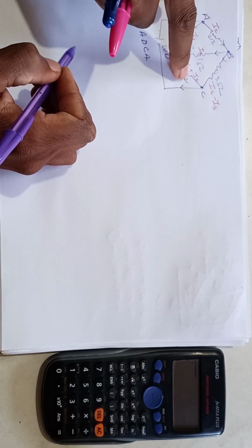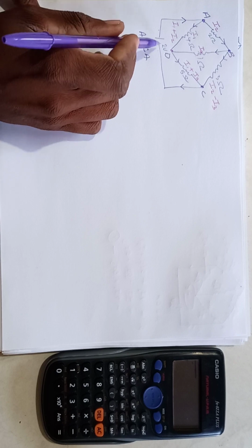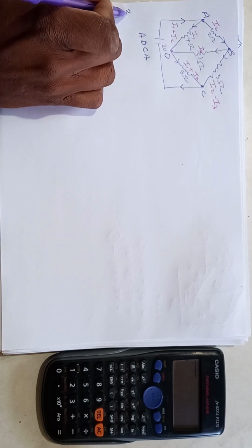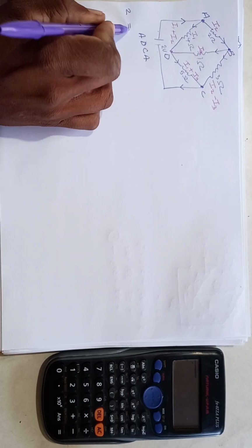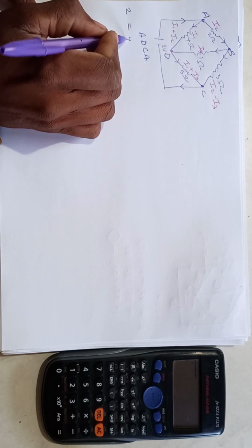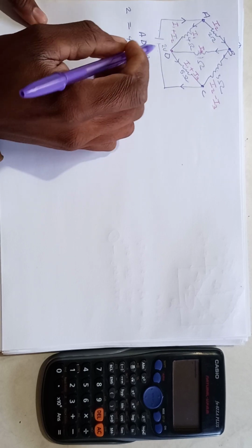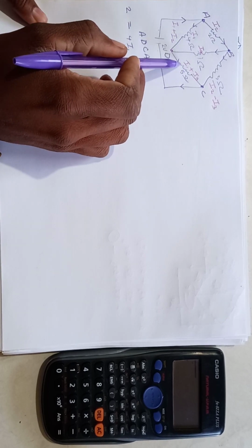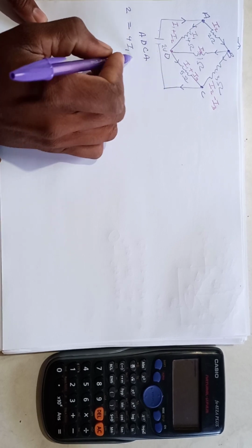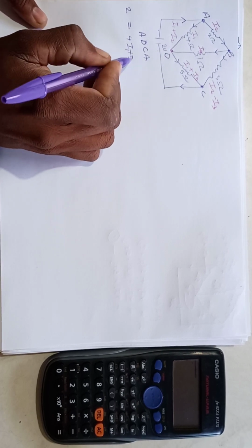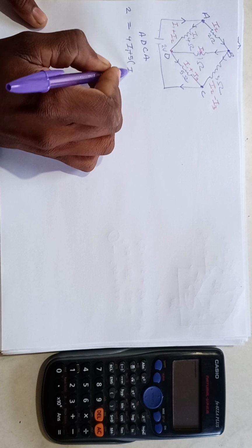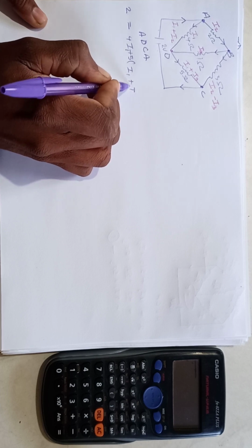So this loop, we have two resistors and we have the cell. So we'd say 2 volts is equal to the resistance there, which is 4I1. And we are going in the same direction even here. So here we've got a 5 ohm resistor. We would add, and we would open the bracket, put I1 plus I3.